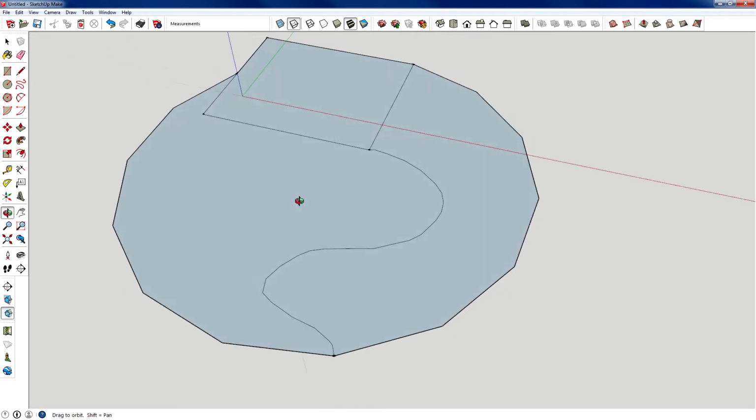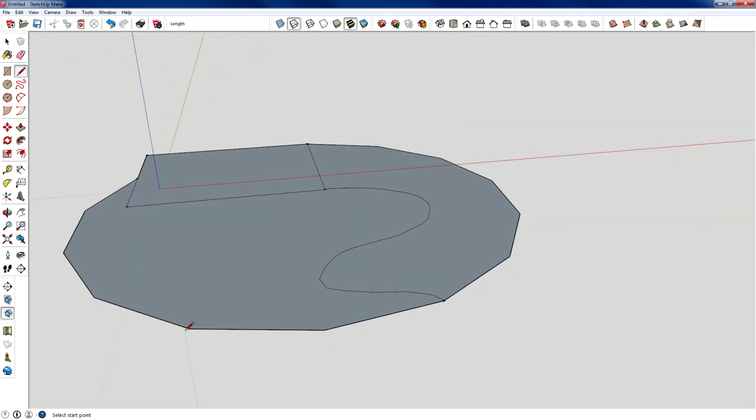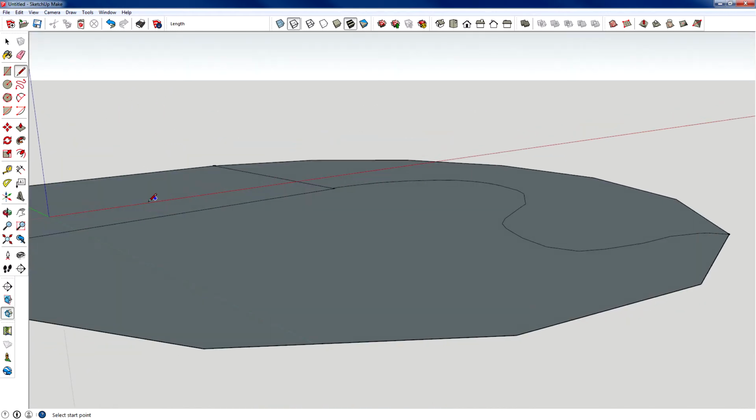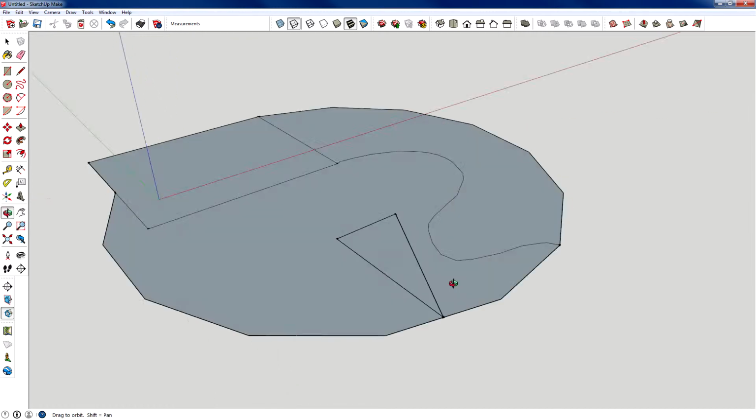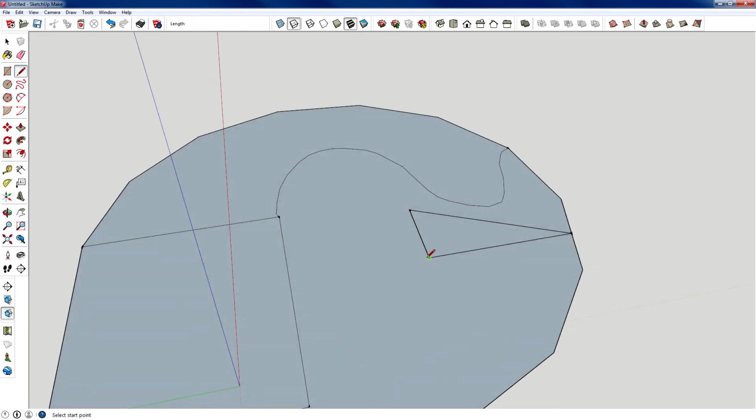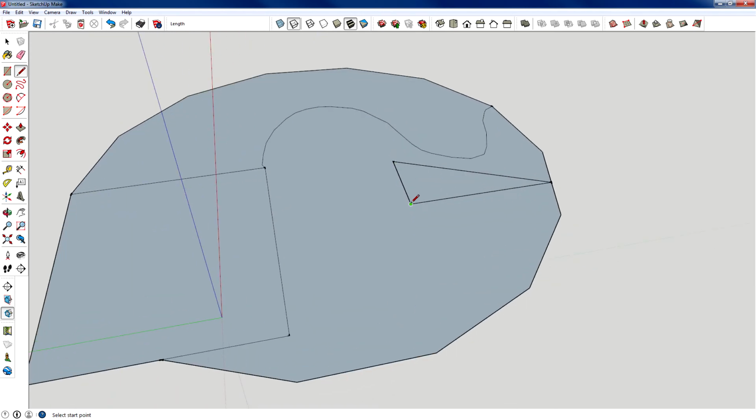You can also use these lines. If we're only dealing with 2 dimensions, we're only dealing with the green and red axes. So if I wanted to draw parallel to it, it'll be highlighted green. Go the other way, red, and so forth. If you see thick lines like this, this means that it's not officially its own plane, like this over here, which is a lot thinner.